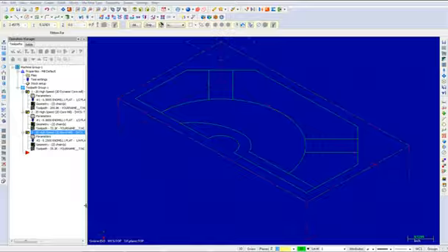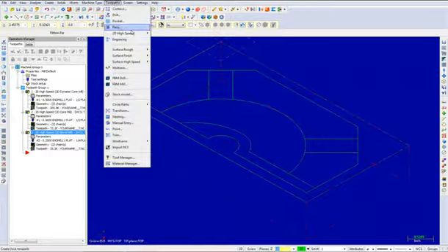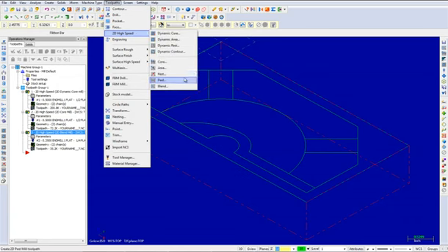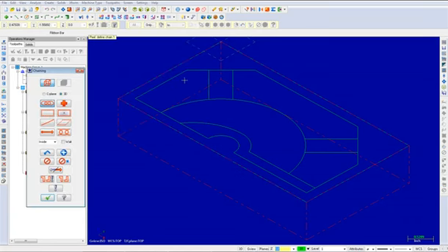Select Toolpaths, 2D High Speed, Peel. Leave the default chaining method and select the following two lines as shown. Ensure that both chains go in the same direction. If your chains do not appear in the same direction, select the reverse button shown here. Once complete, select the OK button to exit the chaining dialog box.